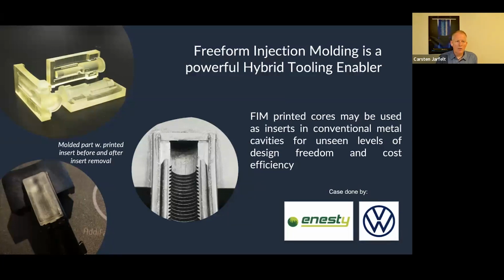Two projects here, just to show you how the combination of printed tools and metal and other tools can be worked. Think of freeform injection molding as a way that you can put stuff into the printed tools, like metal pins and other things, to optimize for surface quality or other things you want to have embedded, inserted and overmolded. Or you can also drop printed inserts made out of xMOLD into large steel tools. So you take out the complexities of those tools.